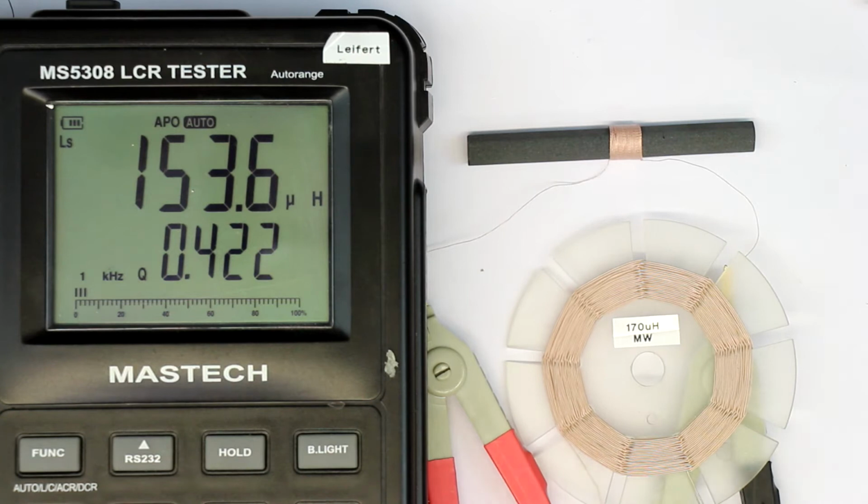So the reason is just a practical reason. If you need or want a small medium wave or long wave antenna, you usually go to ferrite-rod antennas and take the additional losses into account and live with them.